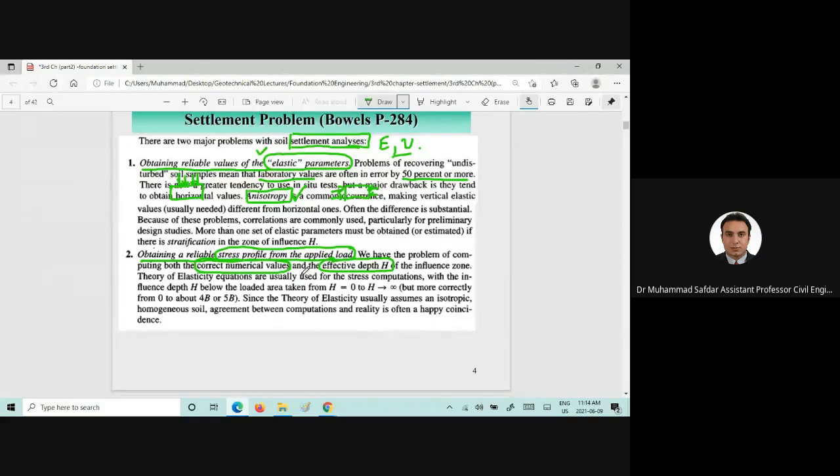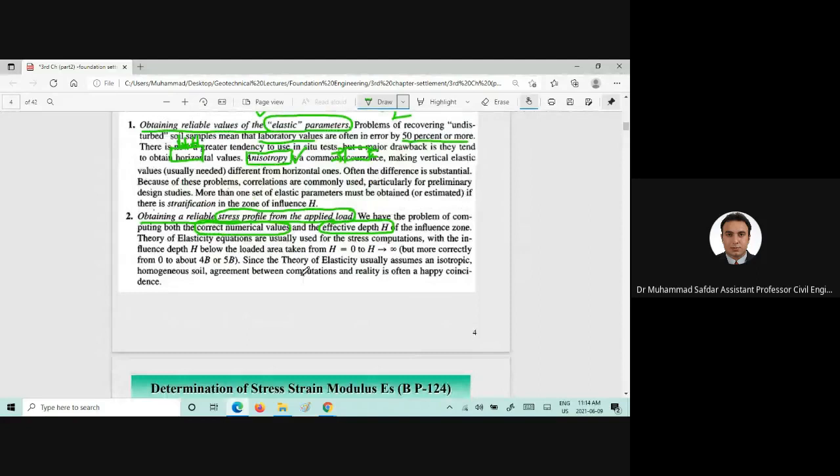We discussed different types of footing. We can go for 2B for the square footing, 6.5B for the strip footing, and 2 times the diameter in the case of circular footing.